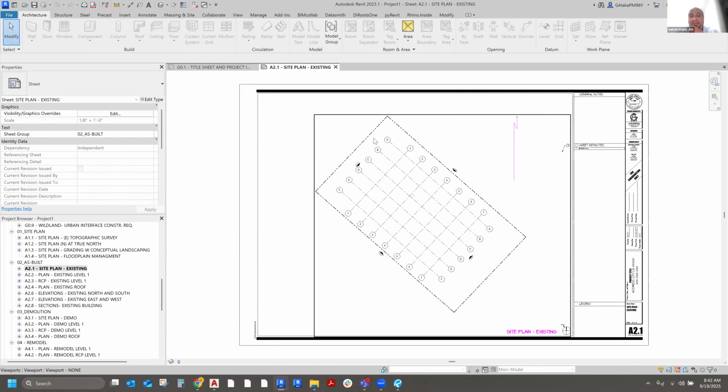But as I was saying, I have all these drawings just waiting for me. I have all these views that are set up, because one of the things about Revit is that setting up your sheets takes a long time. So once you do it one time, you make a template, and from then on, everything is almost pre-populated. But out of the box, Revit doesn't really look like this. This is something you have to develop over time. The first time will probably be the most painful, but every time after that, it gets easier and easier.